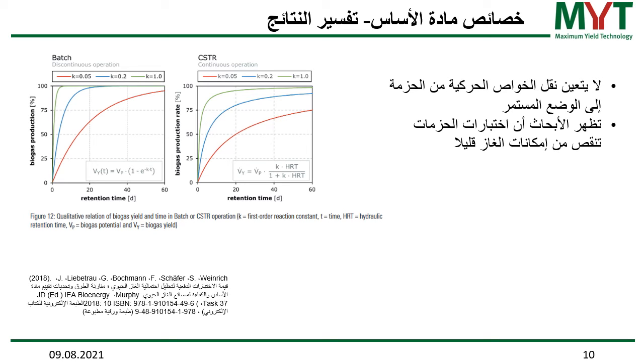As said, the tests deliver different results. It's not only important to know the gas potential or the gas yield. From a batch test you would gain the gas potential. From a CSTR system you would get, in the first place, a certain yield at the specific retention time you're operating at.